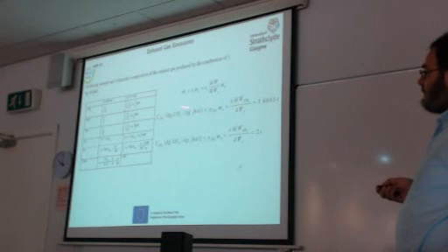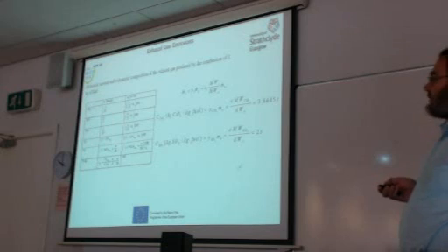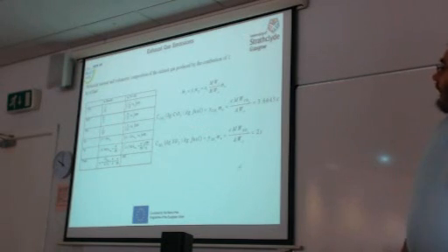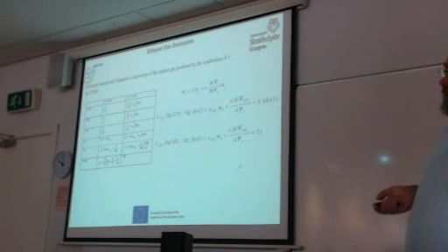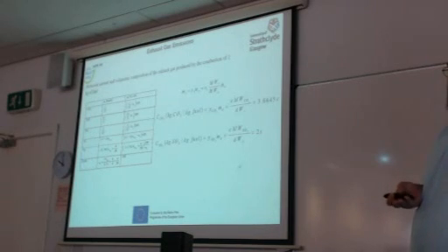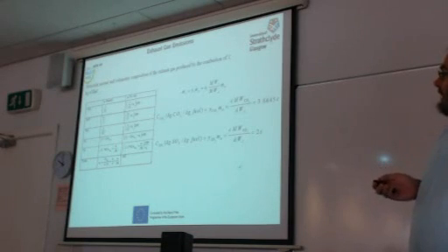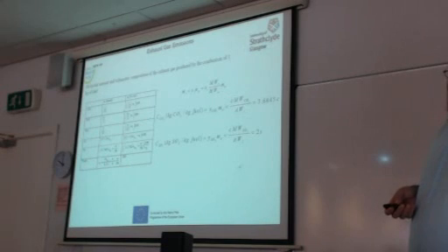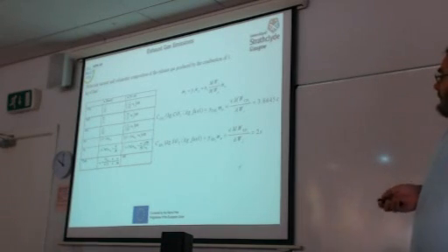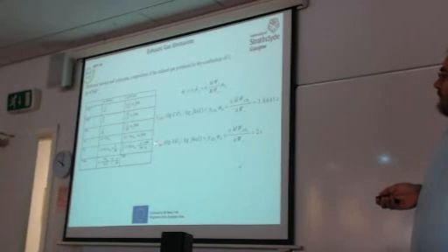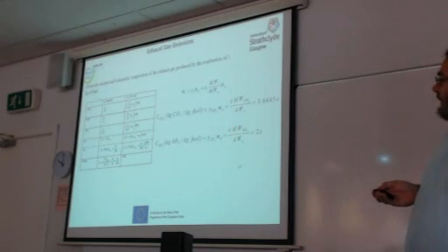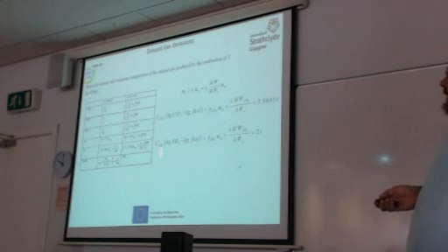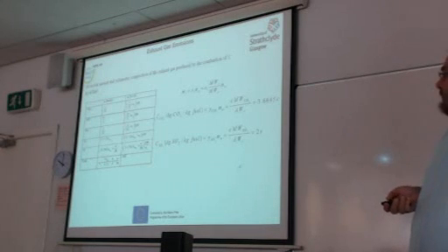So CO2, as we discussed earlier, depends on the fuel content in carbon. So you can see here the emission factor, usually provided by IMO or other sources, in kilograms of CO2 per kilogram of fuel. It depends on the carbon composition of the fuel. And if you remember from a previous slide, for diesel oil we expect 87% or 0.87. We haven't discussed what this C is for the case of natural gas, or for a gaseous fuel like methane. And the SO2 conversion factor, of course, depends, there is a typo here, this is S, on the sulfur content.